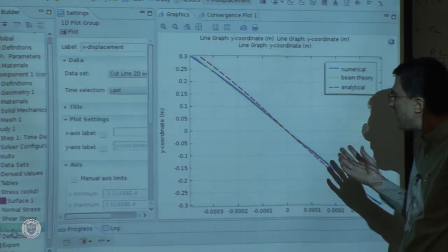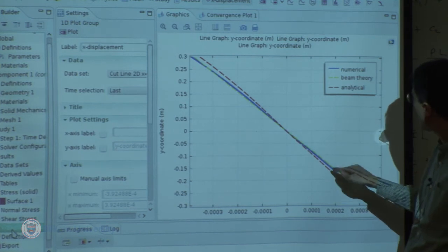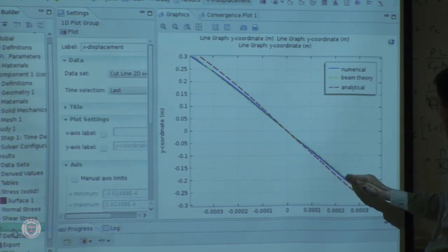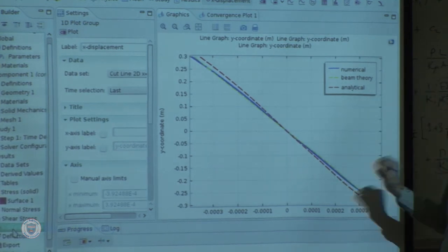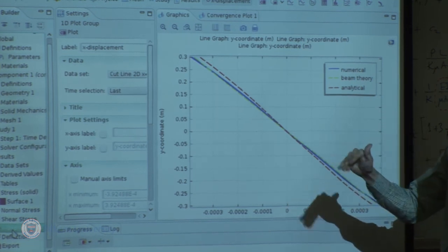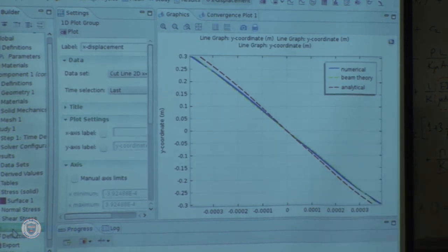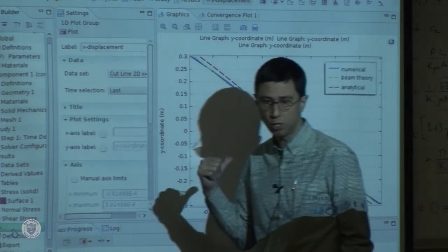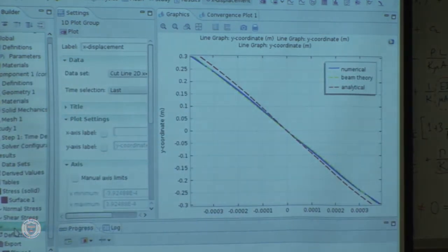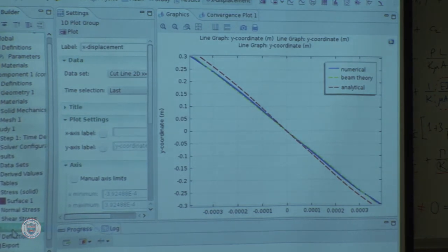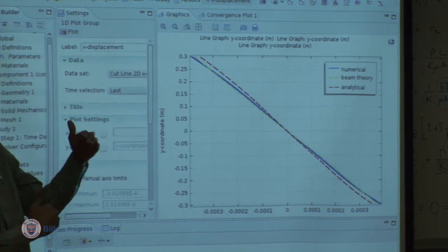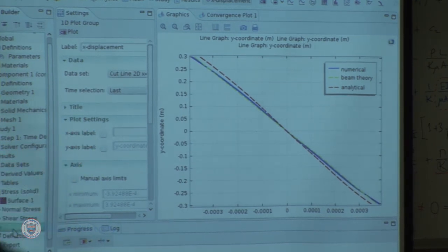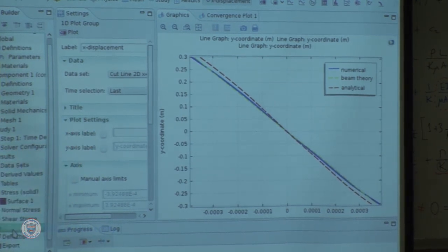So you might be a little bit disappointed by the fact that the red line, which is analytical, seems to be far from blue compared to green. But green is straight, gives you wrong shear stresses. Whereas the red line gives you the good transverse shear stress match that I have already shown. So deflection-wise, it's not very good, but shear stress-wise, it's very good. Again, I don't expect a very good match in deflections anyway. The height is currently very high. There are end effects, so it will dominate, perhaps, features of the solution.